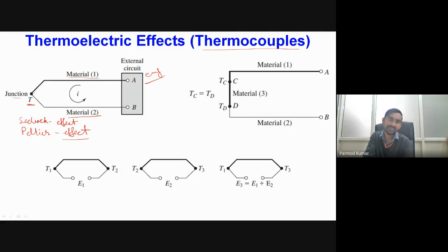Okay, so we will be having certain conduction of the heat along the length of the wire. Because of that, along the length of these measurement wires we will also have some thermal gradients. Ultimately, these thermal gradients will also change the value of the output EMF or output voltage. The alterations in our output voltage because of these thermal gradients inside the wire are particularly known as the Thomson effect.